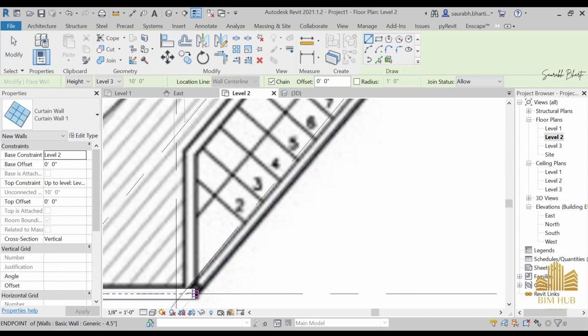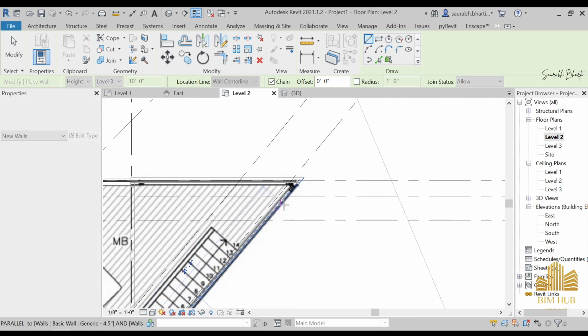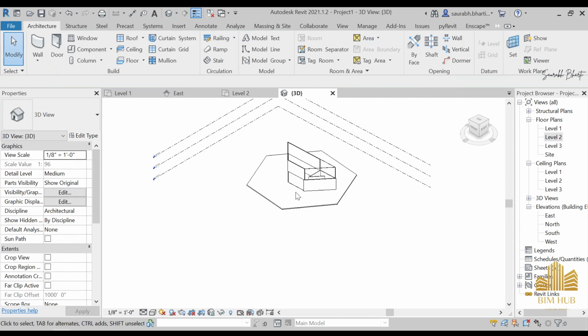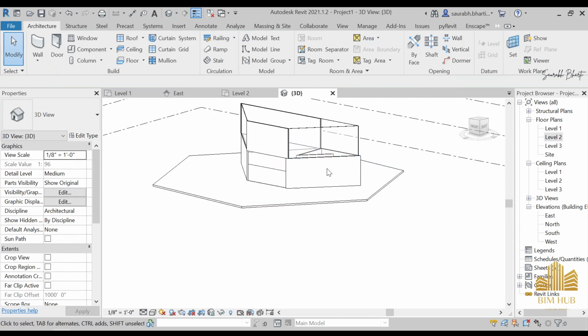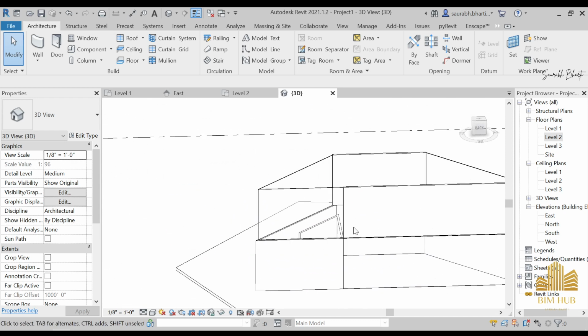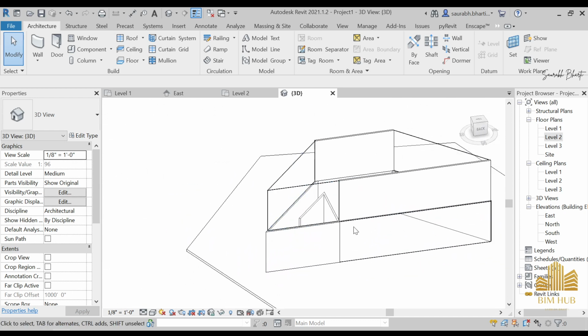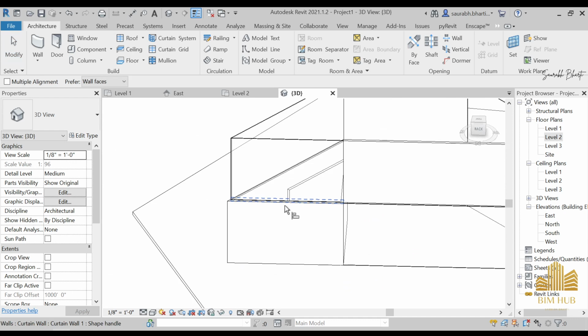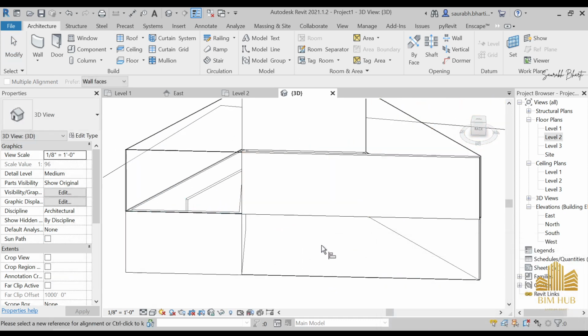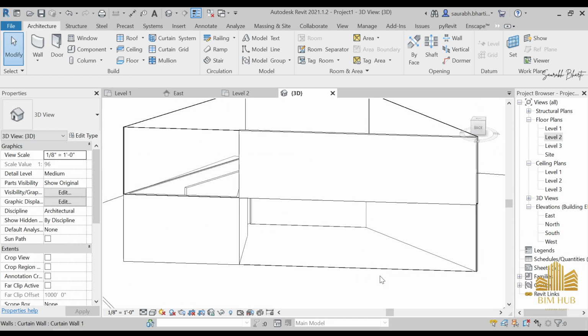And if you get confused, you can rewatch it. So I'm just making it live right now in one go, so I'm trying to do it fast. And now we have every wall over this point. So what we are going to do is, first of all, align every wall. So align this portion to this portion, unjoin element, done. And let me check. Okay, done.